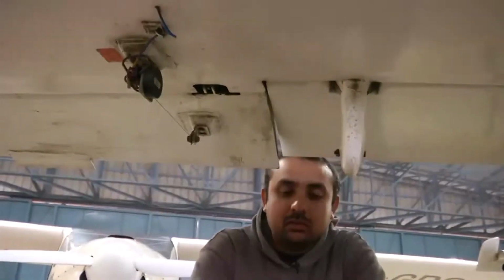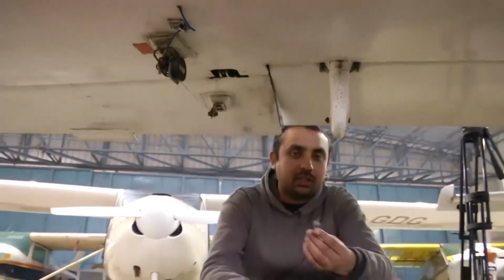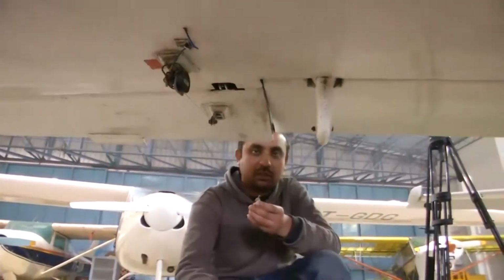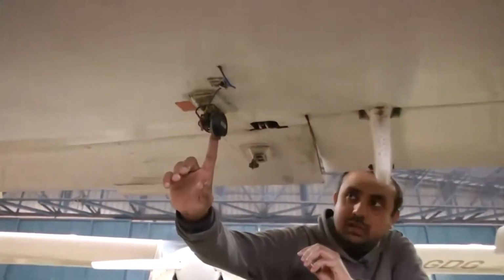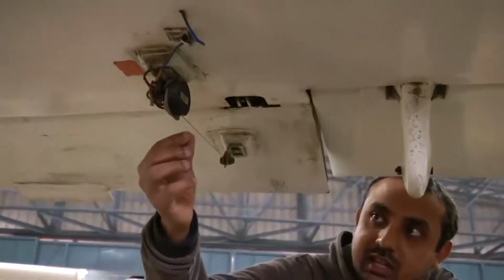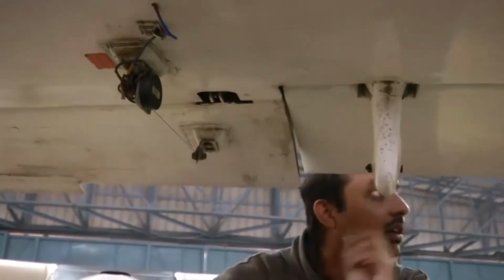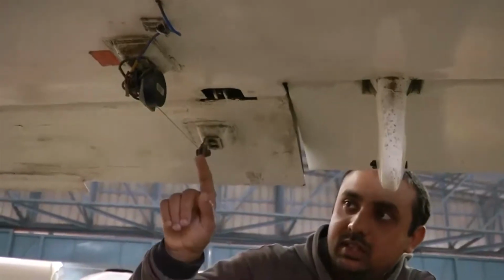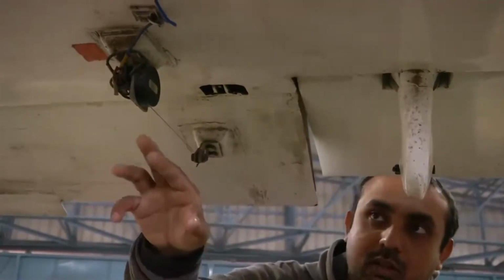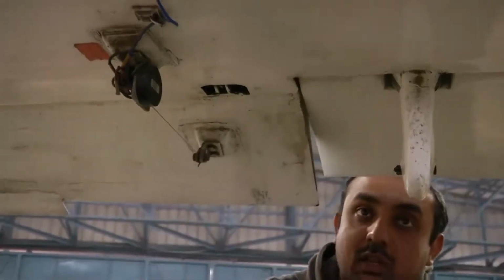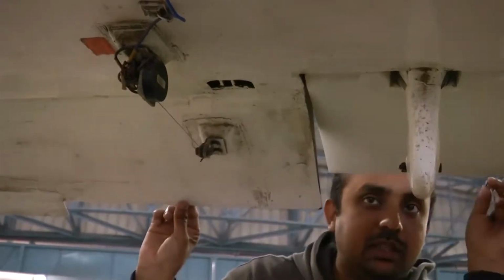Now, I mentioned how to use this potentiometer to determine what will be the deflection of your control surface. The phenomena was same, but for this aircraft, this is your potentiometer. As you can see, a string is attached to your control surface. Now, as my colleague is deflecting control surface, the tension in this string varies, and according to this, your potential or voltage corresponding to a particular deflection in control surface is seen in LabVIEW.